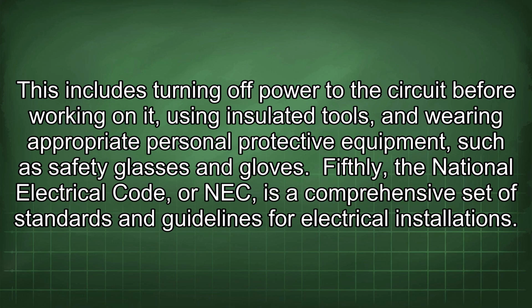This includes turning off power to the circuit before working on it, using insulated tools, and wearing appropriate personal protective equipment such as safety glasses and gloves.